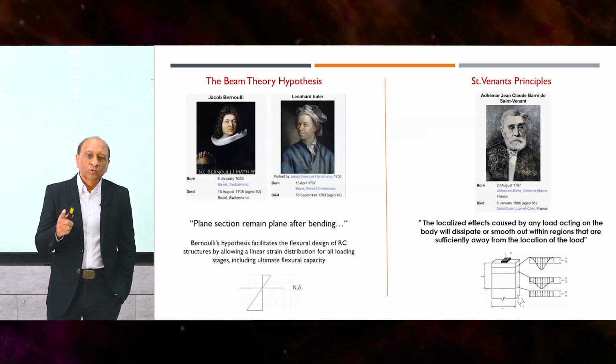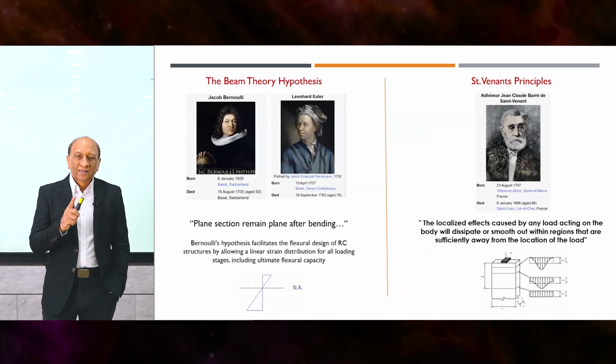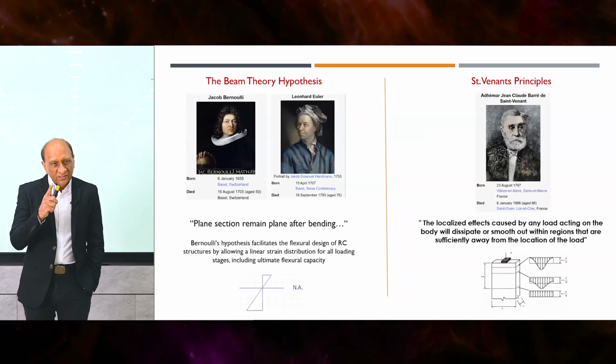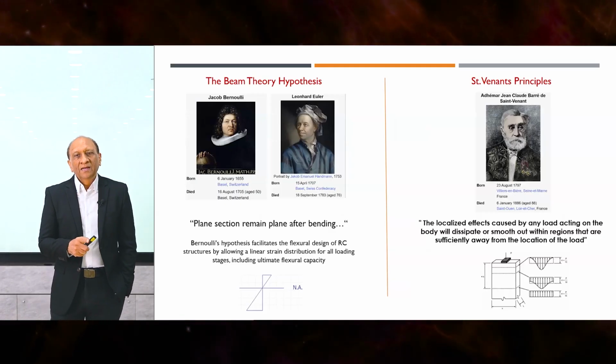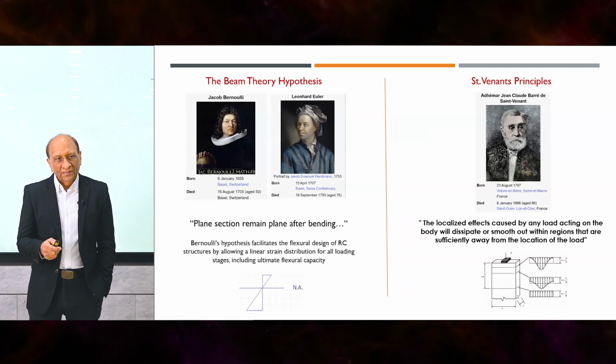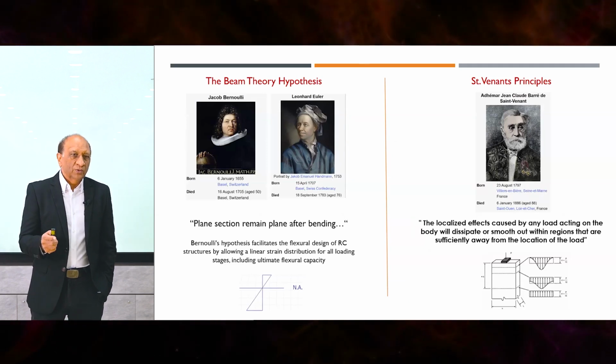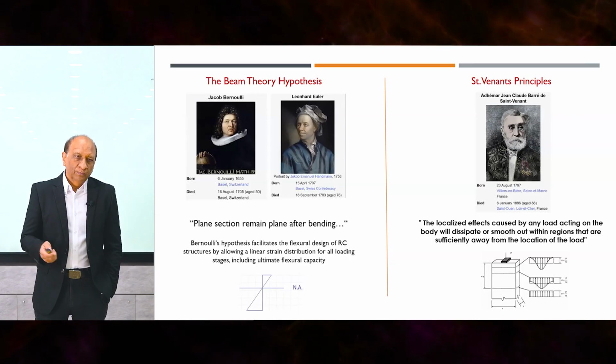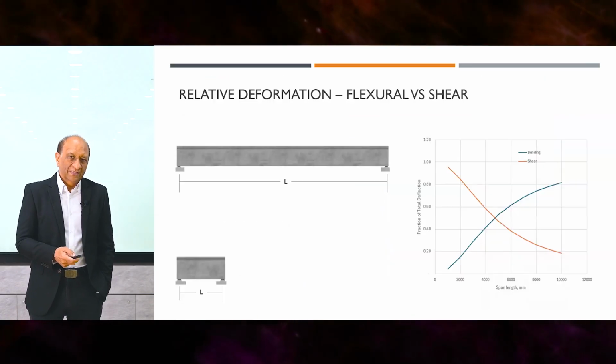But he said that, no, close to the support, close to the points, there's a local disturbance, which alters the plane sections remain plane bending concept. And so this became another important discovery. So these two discoveries together then went ahead to develop most of what we know about the beam design.